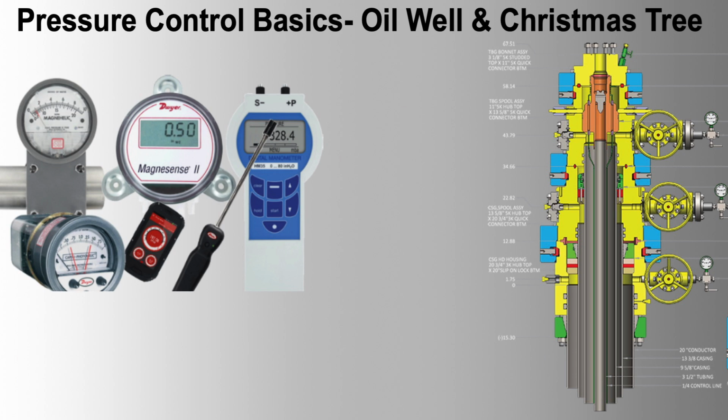Example 3. Annulus pressure monitoring system. Design. Subsea pressure transmitters are designed to operate in extreme underwater conditions. Duplex stainless steel provides the necessary durability and corrosion resistance. Selection. The transmitter's accuracy of 0.2% ensures reliable monitoring of annulus pressure, which is vital for maintaining well integrity. The subsea installation and protective enclosure ensure long-term operation without maintenance.